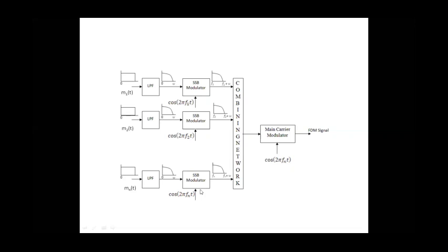That's why one of the needs of modulation is frequency division multiplexing. Okay, just to remember, one of the needs of modulation is frequency division multiplexing. Here, what we are doing in this frequency division multiplexing, we are making use of modulation to achieve the goal, to achieve the aim. Okay, so each and every message signal is shifted to a different frequency range.